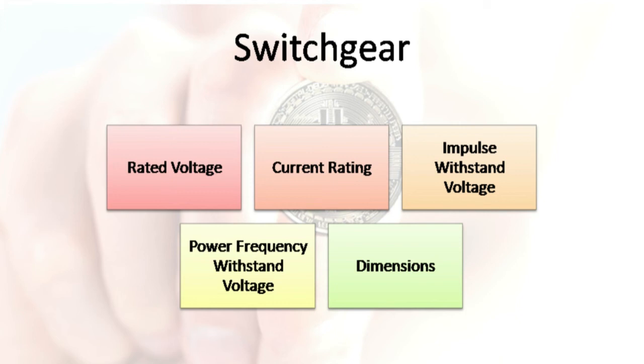If you have a medium voltage directly coming into your mining facility, you most likely would need to have a medium voltage switchgear along with a step-down transformer. Medium voltage switchgear is normally installed in the facility's electrical rooms. The utility feed demarcation point in this case would then be right at the medium voltage switchgear.